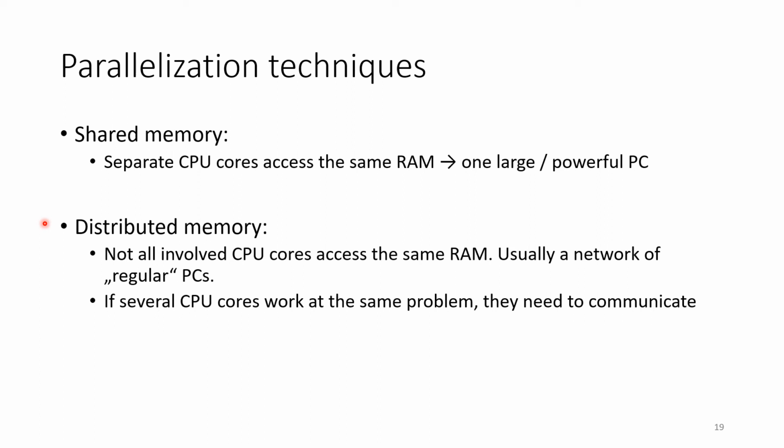Because we want to have a consistent formulation, there may not be a gap between the different domains if you think in terms of a geometrical splitting, parallelization of your code. So at least at the borders of each domain, they need to communicate, they need to exchange the values of their grid points. So there's communication required in distributed memory.